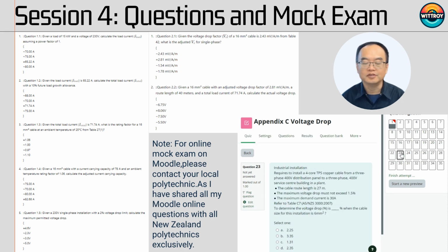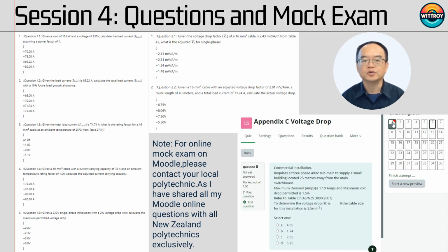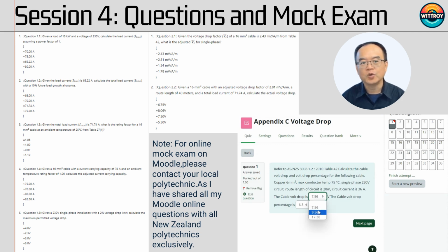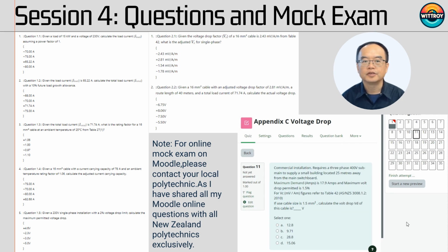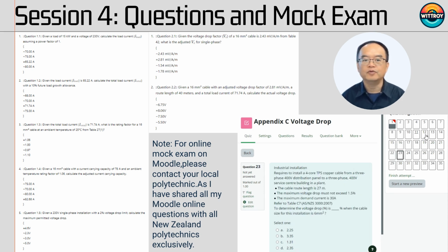I will use the previous example to create a few sample questions using multiple choice type questions. Here is the list of 7 questions. In question 2.1 and 2.2, it brings in the term about the adjusted VC for single phase. It means the 3-phase cable VC from table 42 times 1.155 to get the adjusted VC for single-phase cable VC.